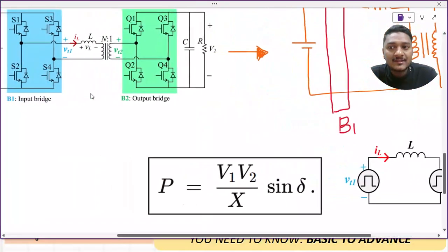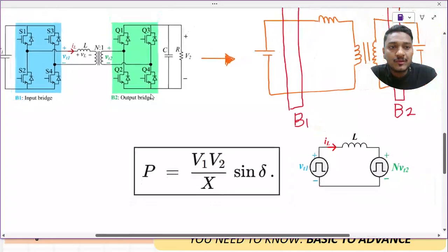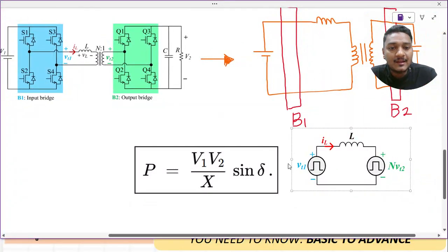Now you can see that the voltage induced at this particular point, V1 of T1 and T2, is a kind of rectangular pulses, some sort of pulse waveform, not a sinusoid. I have marked it like this, and this is the secondary voltage. Can I transfer this to the primary? Yes, using the turns ratio I can transfer it to the primary side. I have marked some sort of figure. Now can I apply the same expression which we derived earlier?